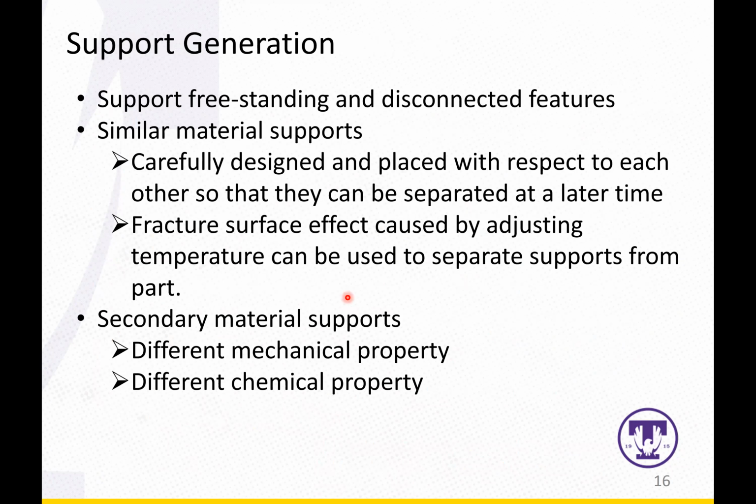So that will be the most convenient way to separate them. But again, it's still a big waste if you print support material, in terms of time and material. And if there's some way to avoid support material, definitely that brings value to the additive manufacturing process.